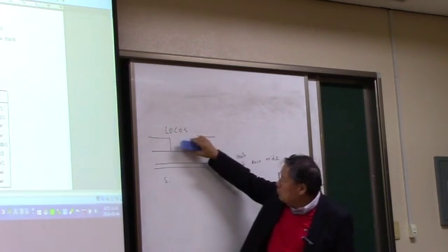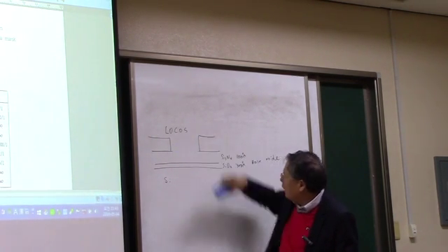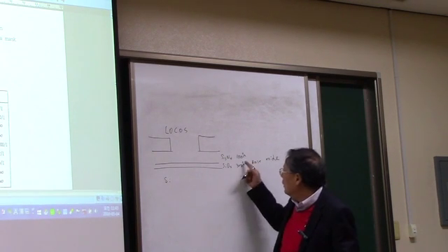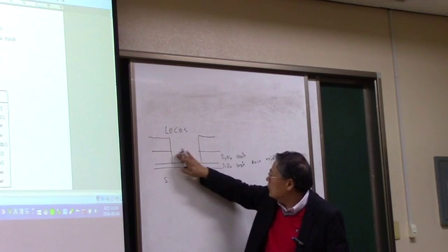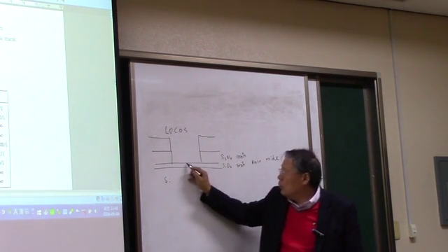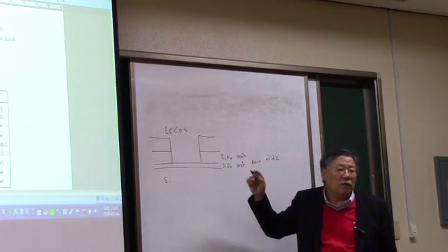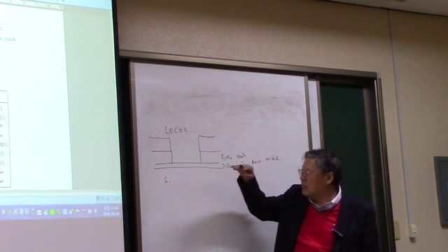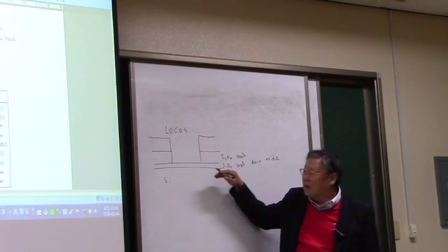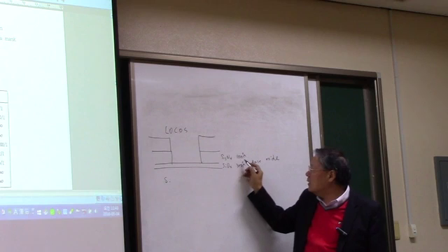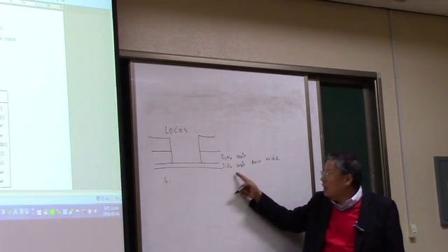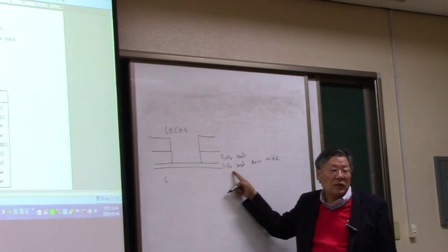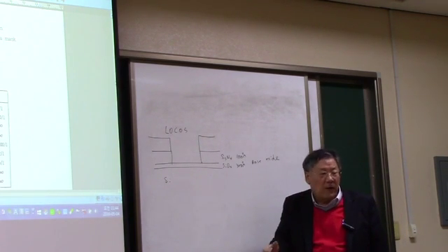So we begin to etch the silicon nitride 1100 like this, and then we do not have to stop the etching process exactly at the time that the 1100 silicon nitride is etched, because the etch rate of silicon oxide is 4 times slower.